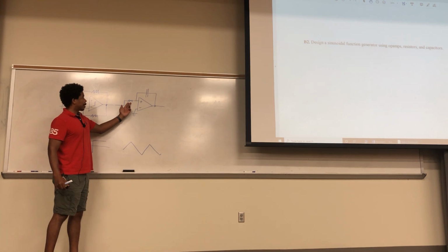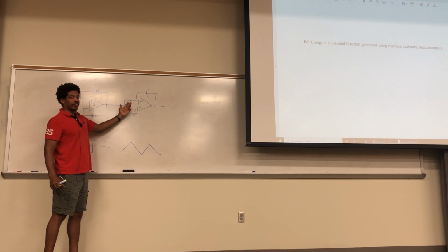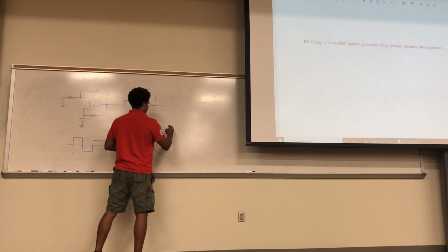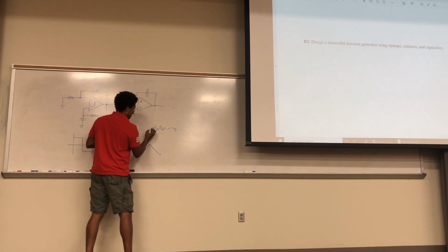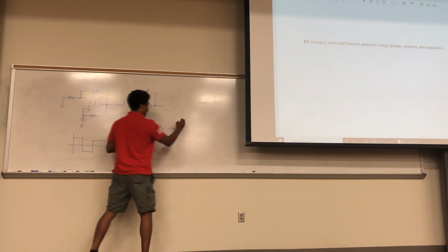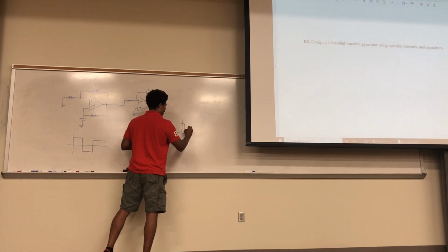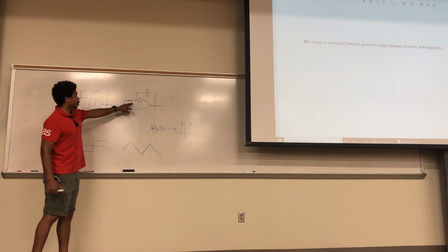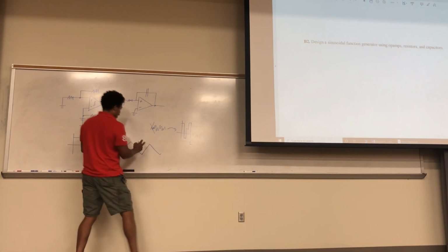If I did do a differentiator, what happens in terms of noise? Why would noise be bad for a differentiator? Huge, yeah. Just think about this. You have this noisy signal, and you're going to differentiate that. You've got a slope here, and right here you have a slope like that. So this thing is going to really jump around. It's going to be bad. Integrators smooth things out. So that's the triangle.